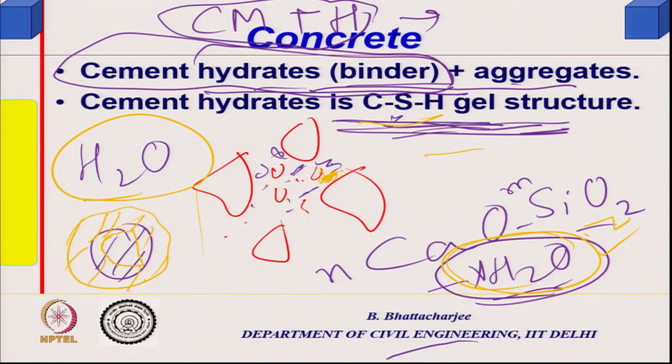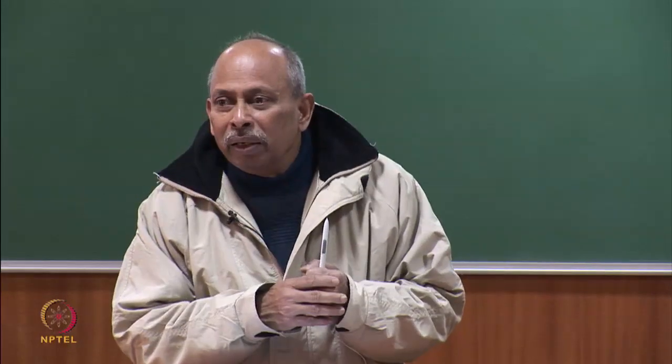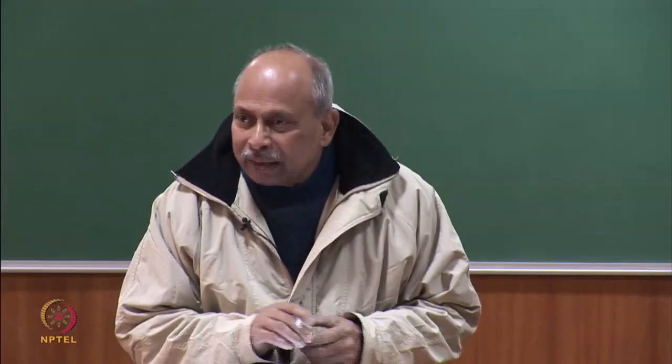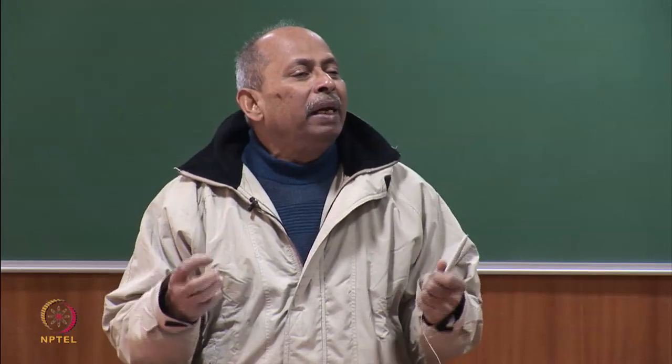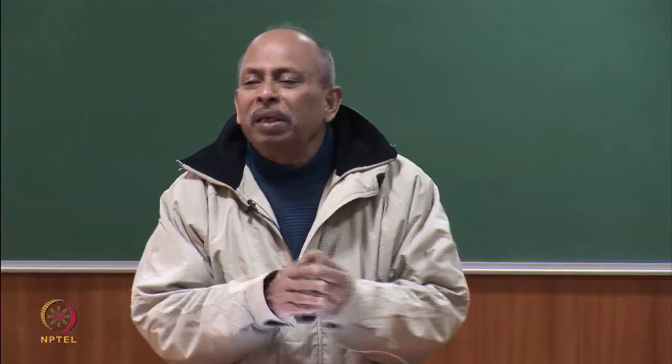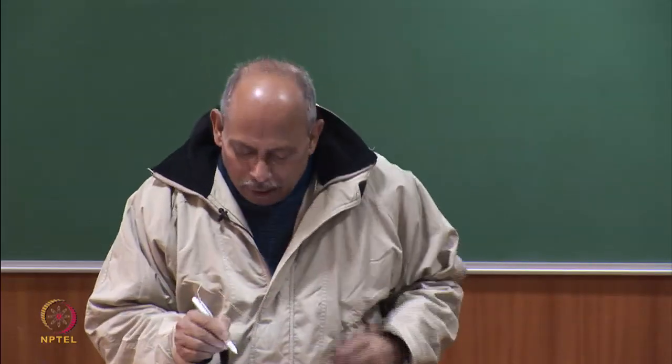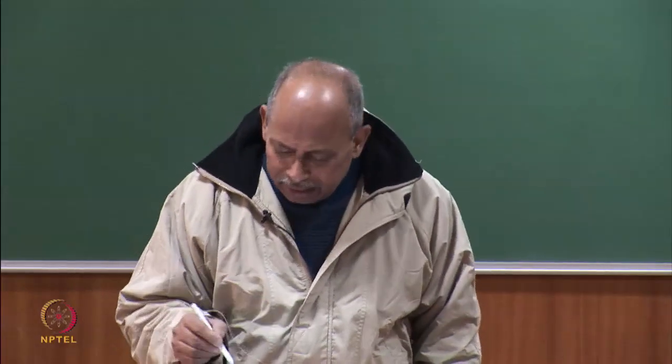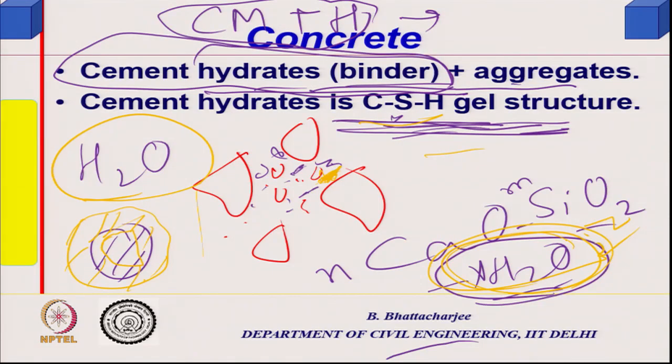So, it tends to become powdery rather than a bonded single solid. When this bond does not exist, it is almost like a pack of sand and aggregate and some fine, loose particles. So, beyond 200 degrees centigrade, this water starts going out. Up to 400 degrees centigrade, most of this water will go out, resulting in loss of bond and strength. So, gradually there is a loss of strength and bond up to 400 degrees centigrade.